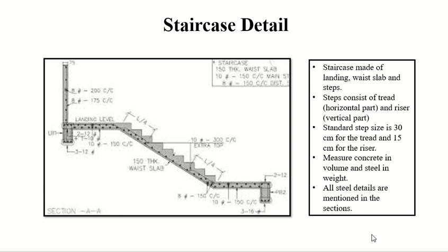And then you have the beams as well. This is the beam here, this is the beam here. Depending upon what you have here, it could be a column, it could be a beam. But under the slab, there's a beam. Under the landing slab, there's a beam. This is very common, for supporting the waist slab. This is connected to the landing. Very rarely will you see columns or beams under this, because it will take your area. It will put extra load and you have to connect it to the footing and so on. So we don't do that.